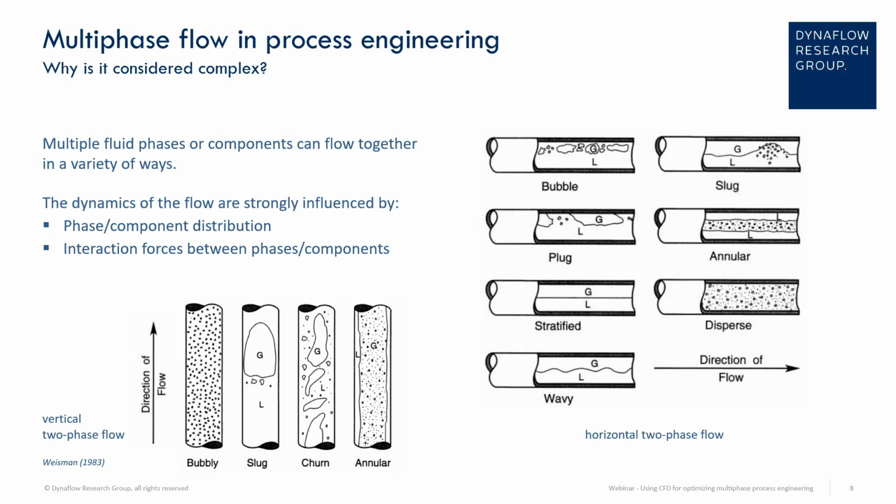Depending on the fractions of gas and liquid, the mixture flow can settle into any of the patterns you see on this slide. For example, if you have a vertical upward flow with a lot of liquid and very little gas, you tend to settle into the bubbly pattern where you have discrete bubbles flowing throughout a continuous liquid carrier. The other extreme in vertical flow would be a situation where you have a lot of gas flowing and very little liquid, in which you have an annular flow, and the gas tends to occupy most of the pipe with some liquid bubbles dispersed throughout, but most of the liquid is in a thin film around the surface, and the liquid is pulled upward by the high velocity gas flow in the center.